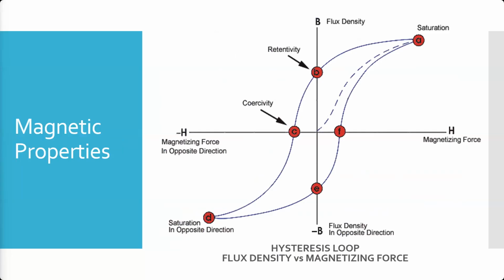It keeps going. So every time we're putting a part in and doing that, it is going to go through those various areas. Now, the nice part is this is happening 60 times a second. It's only at one of these any fraction of a time. If we apply a magnetizing current, an AC current, and we release that button, because this is happening so quickly, most of the time we're going to be somewhere between B and A, or we're going to be between D and E. And so when that current's removed, we're going to end up at the saturation or at the retentivity point.